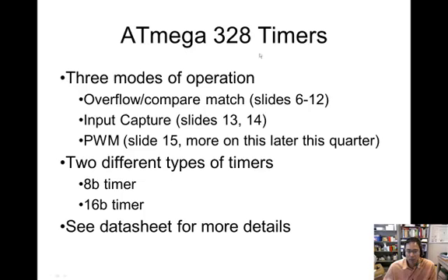One nice thing about the ATmega 328 is that there are different prescalers that we can use as well, ranging from 1 up to 1024, so you can divide your system clock down by about 1,000 before even sending it to the timer. There's also an asynchronous mode, where the timer's clock source could come from outside the chip. Of course, you have to provide it a clock then. It also has an input capture mode. It can count the amount of time between times when the pin went high or something like that. And then it also has pulse width mode, and we talked about that.